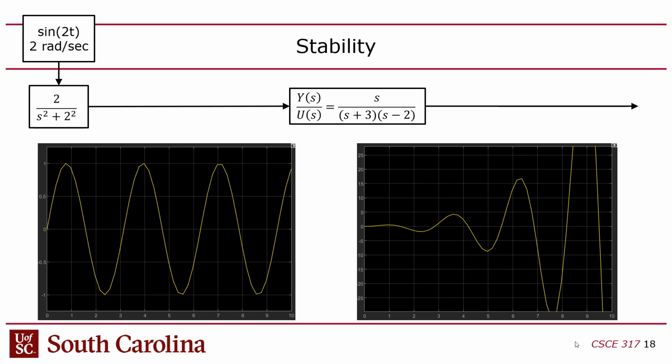But anyway, the point of this is that if you take that and you multiply it against your open loop transfer function, then you can find the poles and check for stability, or you can just run a simulation, right? Now this is an example of a simulation where it's not stable. Look what happens. It kind of blows up.